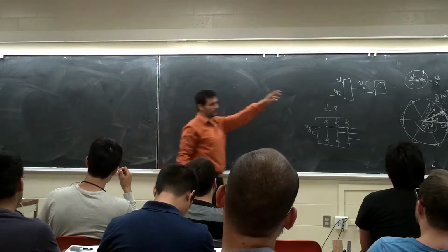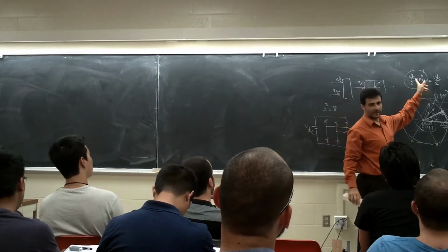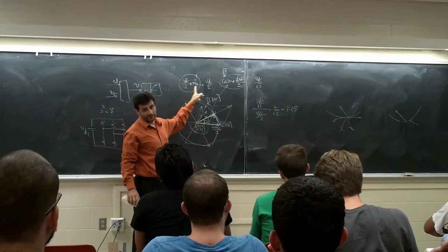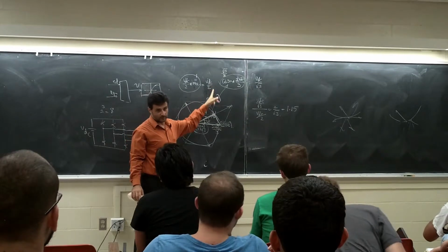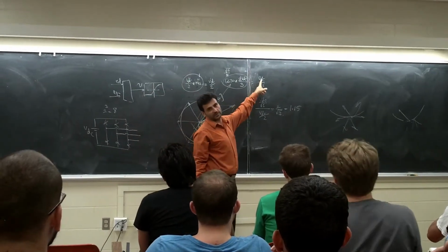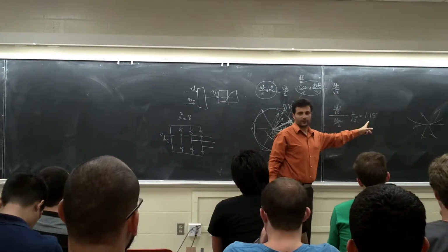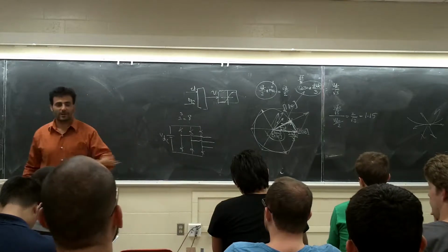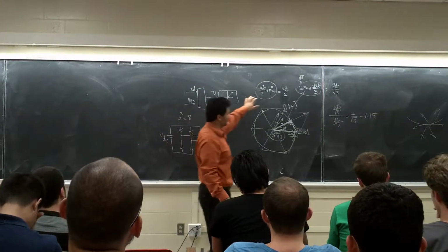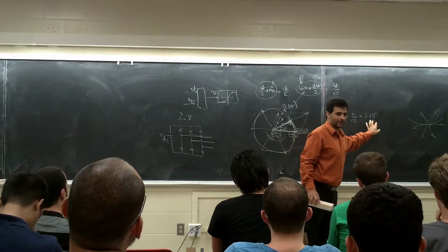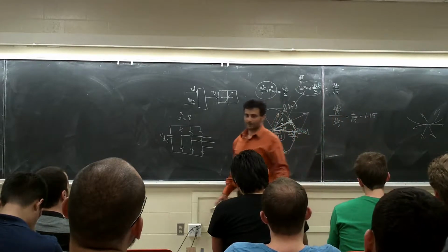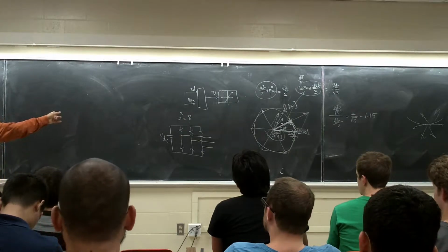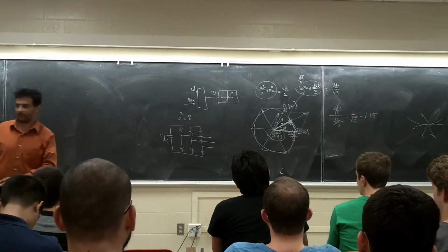So basically, this one is coming from the sine PWM, where the maximum phase voltage is VDC over 2. With space vector it is VDC over square root of 3, and if you divide it, you're going to get here. It means the maximum phase voltage with the same DC bus. If this one can give you 100, this one can give you 115 volts, right? Or you can go opposite. If I want 100, that one has to be bigger VDC, and this one could be less DC, right? And I explained that.